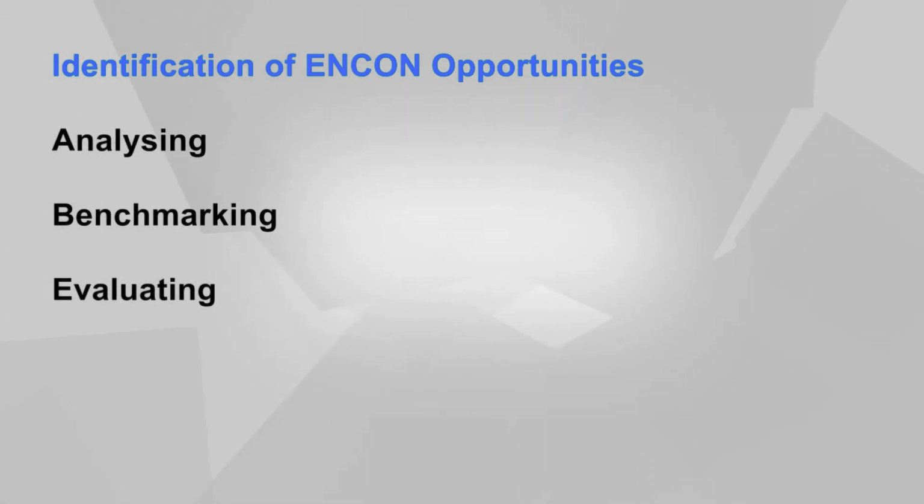The facility description and energy use profile is a section discussing the physical characteristics and operational details of the audited facilities, which includes information about the building envelope, HVAC systems, lighting, equipment, and any other relevant energy consuming systems. The energy use profile presents a breakdown of energy consumption by source, that is electricity, natural gas, and end use like lighting, heating, and production processes. It may also include historical energy consumption data, energy intensity metrics, and benchmarking against similar facilities or energy standards.